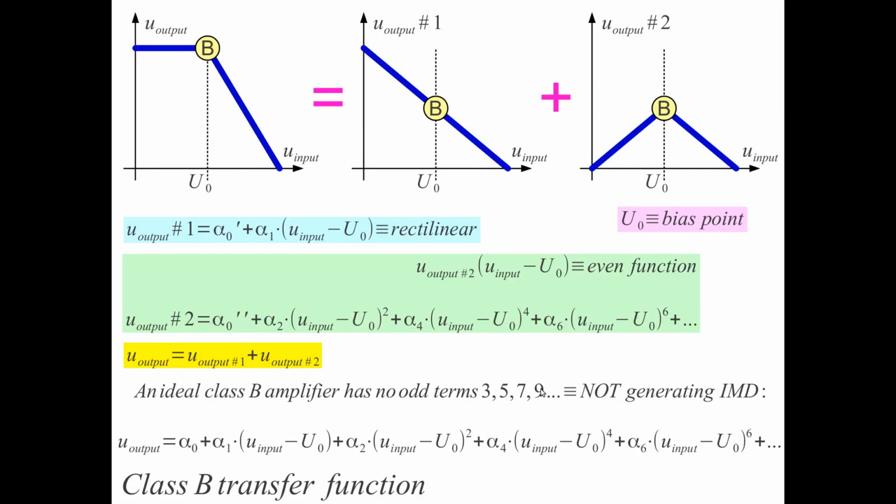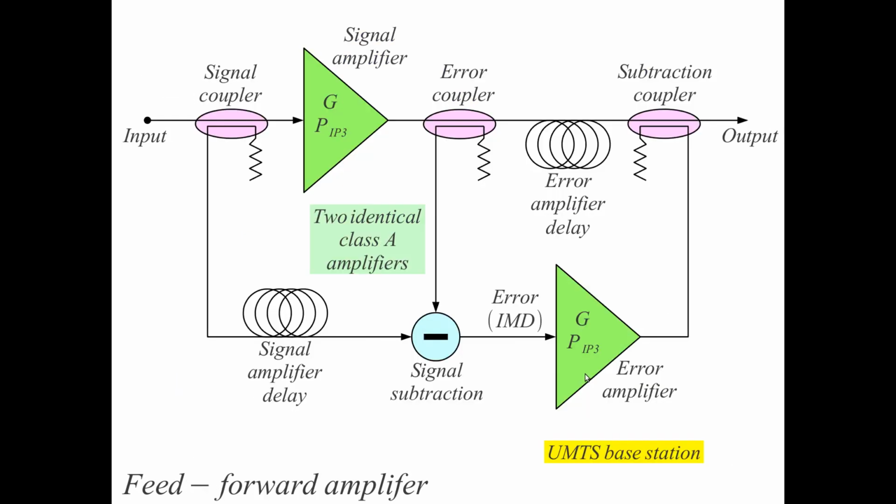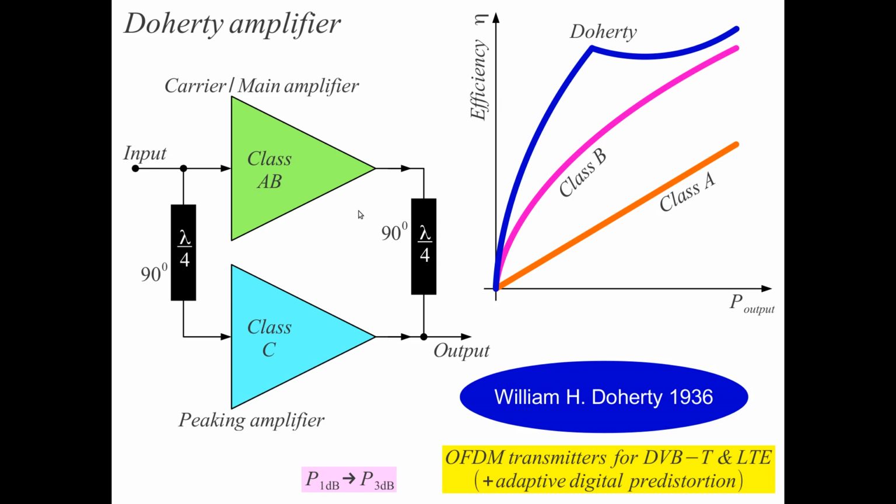For higher power systems, we resort to Doherty amplifiers with digital predistortion, with adaptive digital bias adjustment of both stages to have better efficiency.